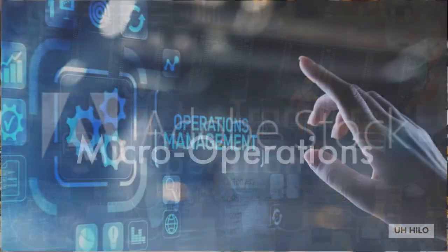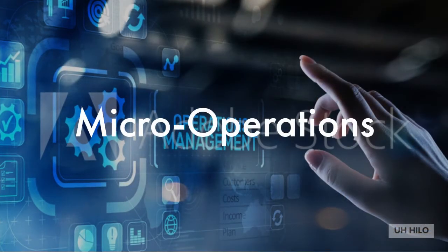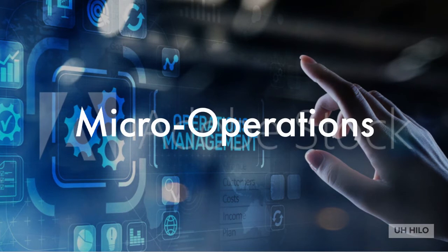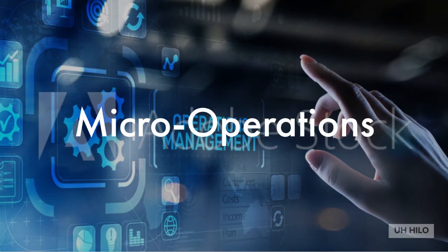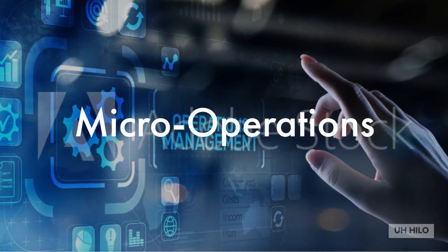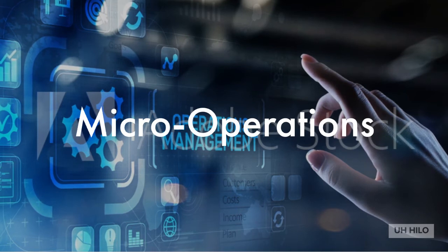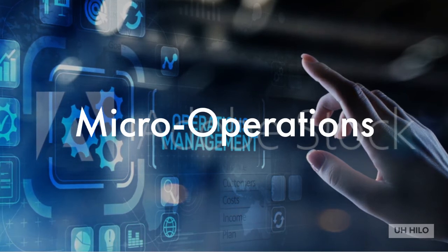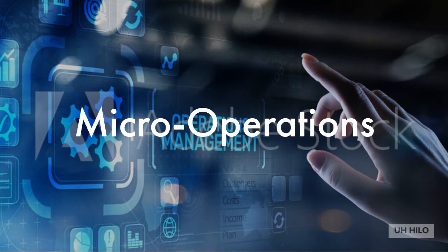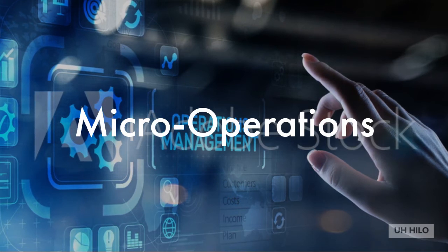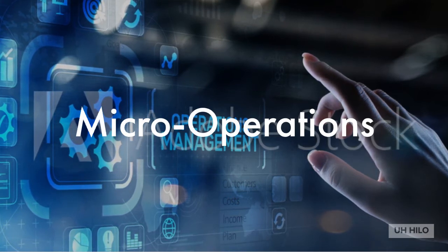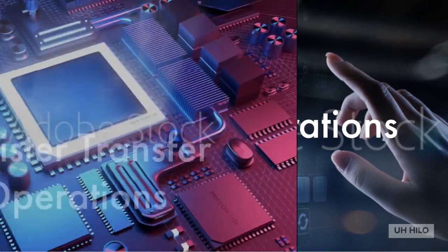An elementary operation performed on data stored in registers is called a micro-operation. Examples of micro-operations are loading the content of one register into another, adding the contents of two registers, and incrementing the contents of a register. A micro-operation is usually, but not always, performed in parallel on a vector of bits during one clock cycle.